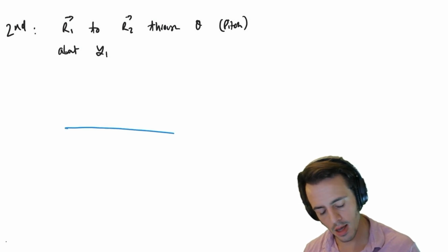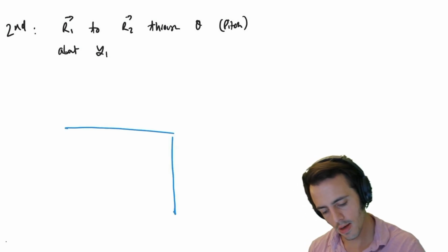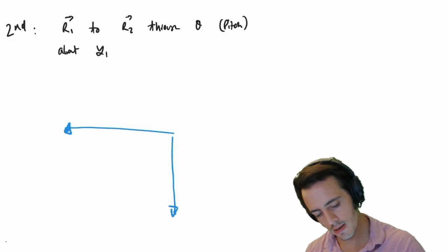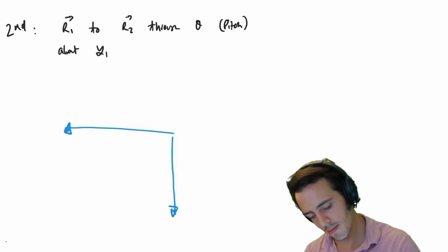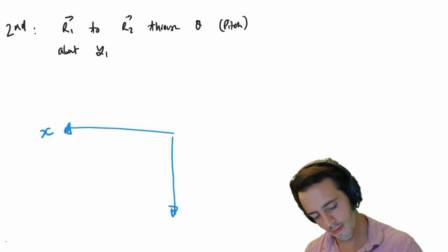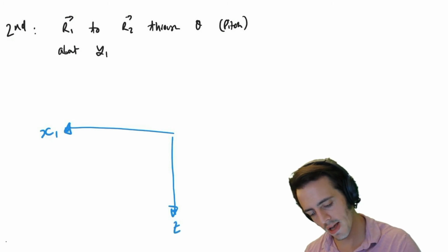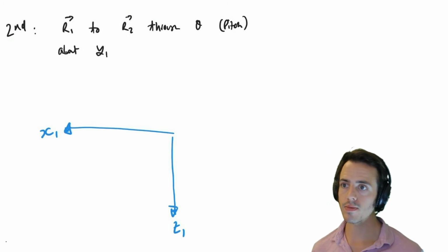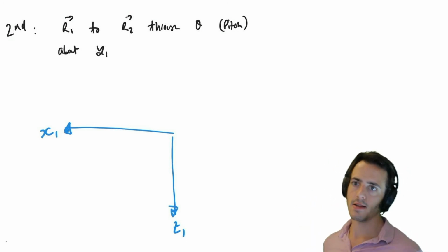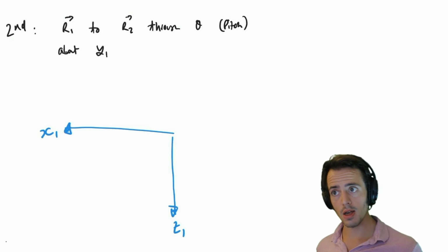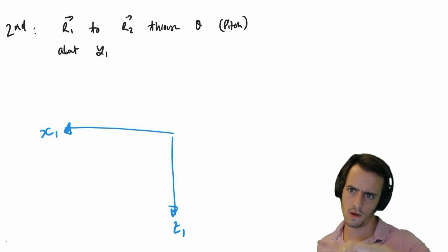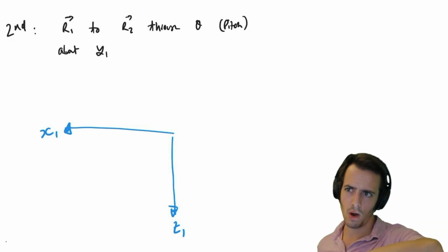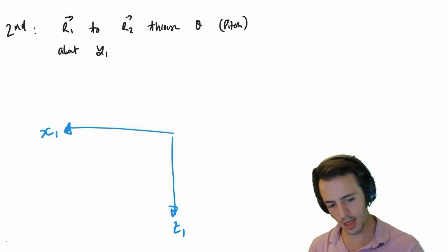Let's say I'm going to draw X and Z. Okay, so my unrotated axis set is my intermediate 1 in this case. So if this is my axis set, then the direction of positive rotation, so that's X, Z, so Y is pointing into the page. Wrap my thumb around Y, it's going to be a clockwise rotation again.